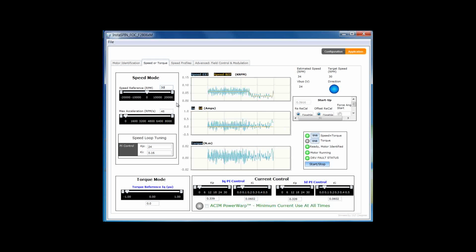So at 30 RPMs, you can see it actually dropped pretty low there. It's because there was no load. And so when there's no load, the back EMF is getting very small. And so I'm able to run here now a light load at 30 RPMs very well.